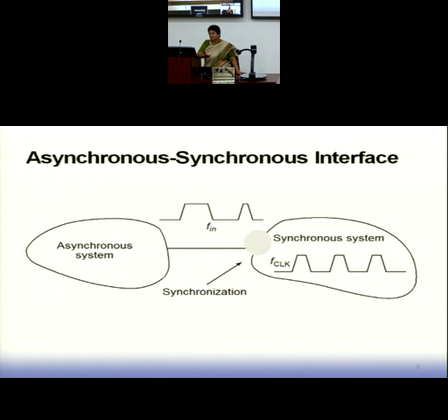It is confusing whether it is logic 1 or logic 0, whether it is more than the switching threshold or less than the switching threshold, we don't know. It is between VIH and VIL. I don't know what this value is. It can be anything. So your next system to which it is going as an input may treat it like an input 1, or it may treat it like an input 0.